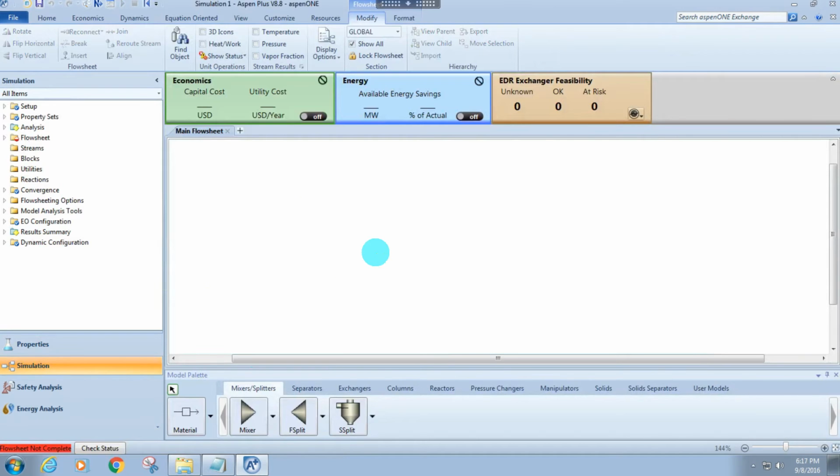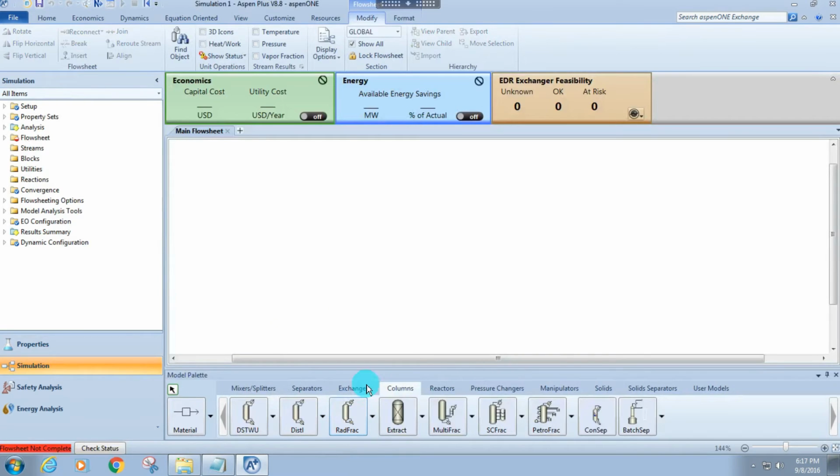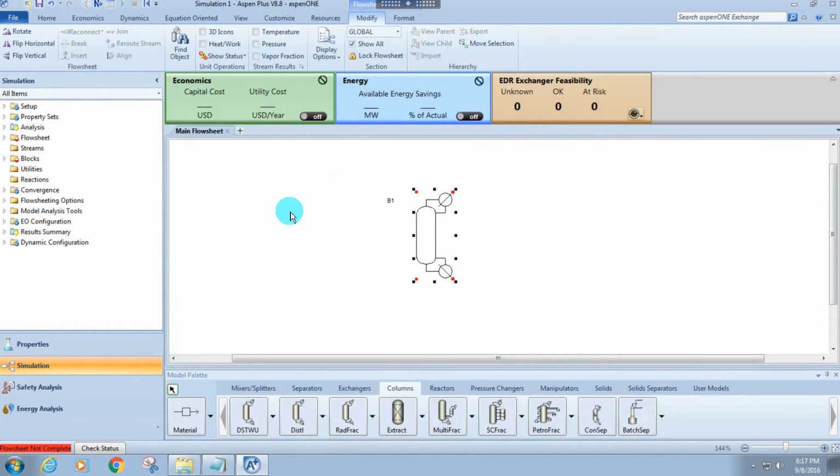Now, as I said before, we'll do a pressure swing distillation with tetrahydrofuran. So for a distillation column, we will specifically use the RadFrac block in ASPEN. I think it is the most rigorous calculation for distillation, and it is the most reliable. So we put our block down. I just like to turn off 3D icons. I just think it's cleaner this way. It actually looks like a PFD that you might see in industry, or like the ones you've seen in your internships or co-ops or whatnot.